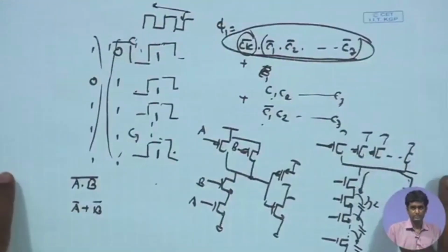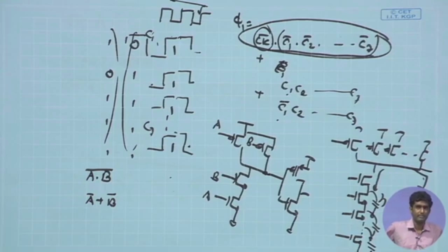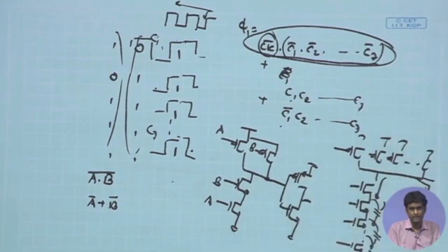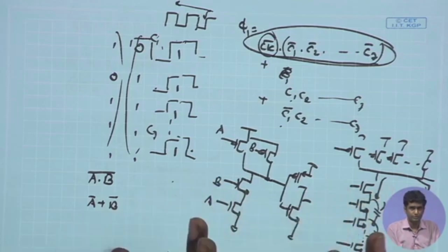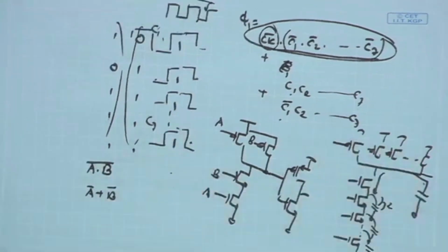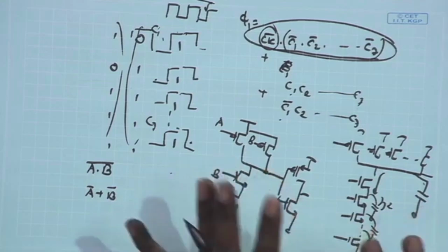Any question before we end this discussion? So, we have basically covered the building blocks of our ADC in sufficient detail, starting from the ramping circuitry, comparators, their non-idealities, sampling circuitry, along with the comparator design, its specifications, its non-idealities, including offset cancellation, and finally, we also came into the digital controller part, where although the control is simple, we dealt with the constituent elements at block level, the overall functionality of the control operation, how the pulses are getting generated, and finally, we went into the transistor level implementation of all those digital blocks, looking into the important definitions and issues at transistor level implementation of those digital components.